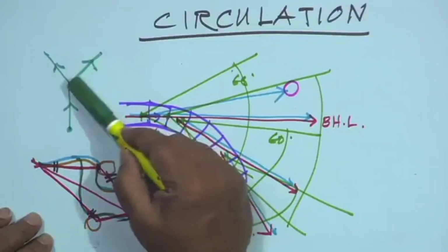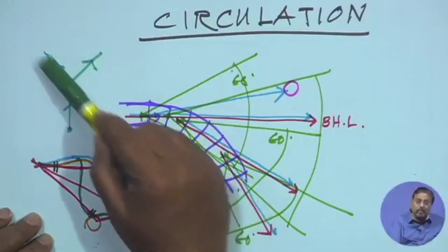He has now equal options, either to go to the right or to the left in the Y. When you are splitting these routes, if you want that one should follow the right path, not this, you make this primary and this secondary. To make the primary and secondary, you change the scale or the character of the circulation path. That means, you make this wider and make this narrower. The moment you make this narrower and this wider in a Y junction, immediately the mind starts reacting to it and infers this wider road probably is meant as a primary road and the second one is secondary one.